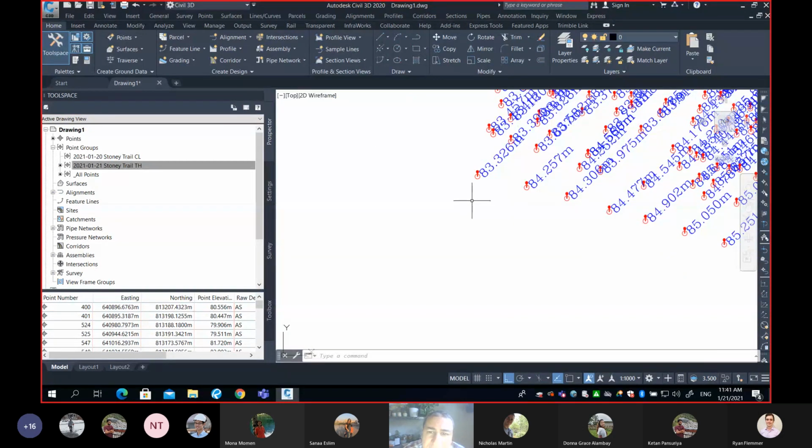Now, in this class, I want you to take a summary, because that's very important. You need to understand what you learned in the entire class today. You have learned the structure of the files that the Total Station produces. You also have learned how to import the points into Civil 3D and how to take care of all the elements where you have to say, where is the file? What is the file format? You need to check the preview and add the points to a point group.